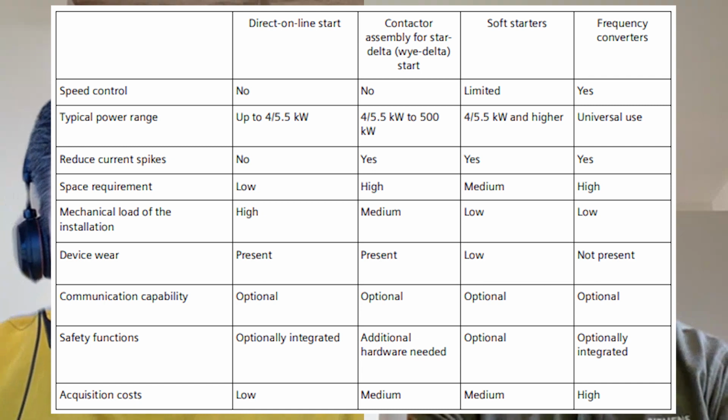Yeah, so there are quite a number of factors to consider for starting motors. If we take some of the examples you mentioned about impact load for DOL as against a smooth transition if you're using a VSD, obviously one will be a cheaper option, one will be a more expensive option, but it really does depend on the overall cost of running that application and also making sure that you want to limit any stress factors, for example.